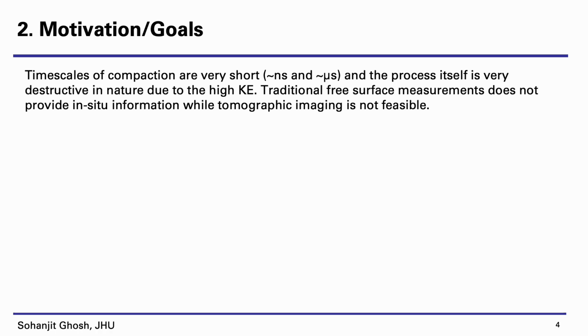So traditional gas gun experiments, like high velocity impact experiments, use free surface velocity measurements like photon Doppler velocimetry, but that will not give us the in situ information that we are interested in. We want to understand what's happening inside the granular assembly, in between the grains. While tomography, something like X-ray tomography, is a very slow process and cannot be used in destructive settings.